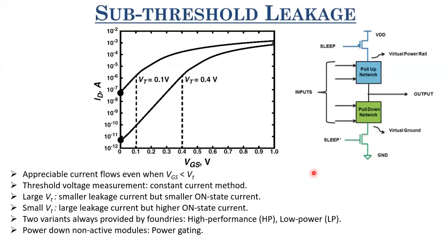It is used in almost all the processors nowadays, and power gating is used to minimize the leakage power dissipation, because the levels of leakage that we are getting in modern transistors are pretty huge. Unless we do innovations in the transistor as well as architecture level as well as circuit level, it's not possible to mitigate. So this is a kind of innovation at architecture as well as circuit level, because we are introducing these two extra transistors which minimize the leakage current through these logic gates.